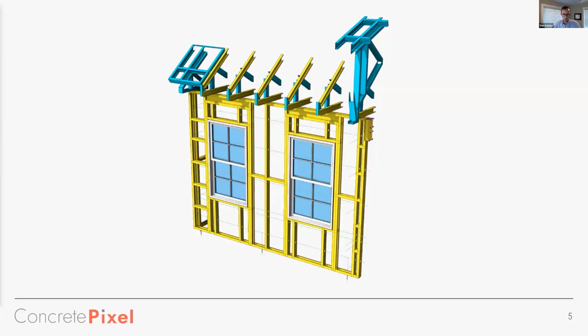This is an image of a wall panel, and it's just a small sampling, but it does show several different components integrated under this umbrella. You have your stud gauge and sizing, so your profile sizes, 18 gauge, 20 gauge, etc. Stud spacing, which is 24 inches on center as shown. Horizontal bracing, mid-span of studs. Your king studs, which can change depending on structural loads. Shown here, they're double kings. The header configuration, sizes, gauges.